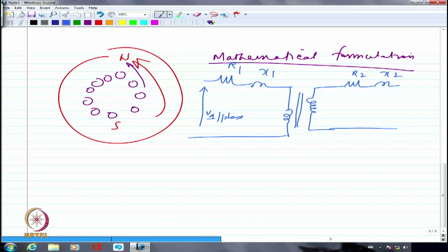I have to short circuit, definitely. I am first starting off with open circuit, and I know for sure that it would have been V2 at the terminal, because hardly any current flows. In the primary also very limited current, hopefully. So I'm going to have V2 as the induced EMF. I'm not unduly bothered about that, because, as he correctly pointed out, I have to short circuit. So I have short circuited it.